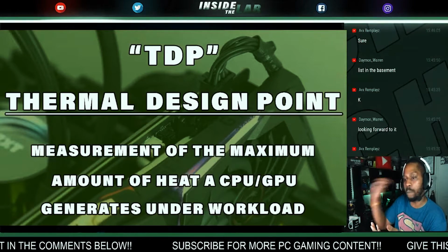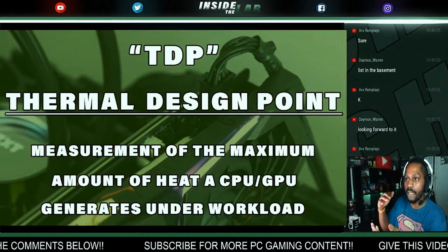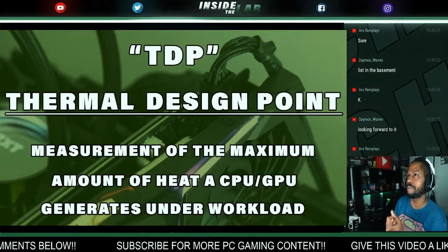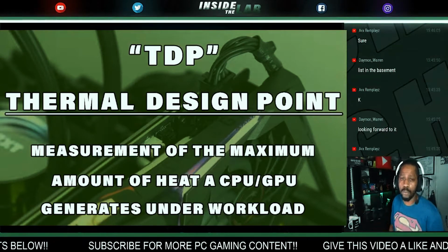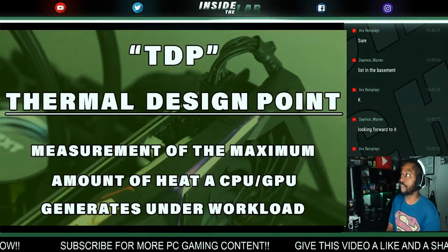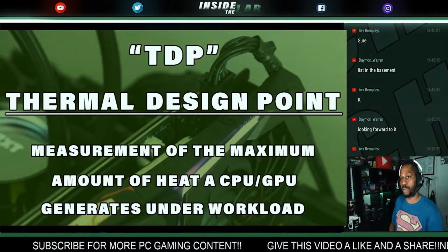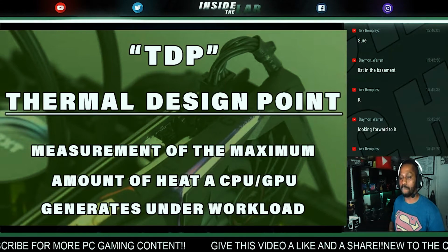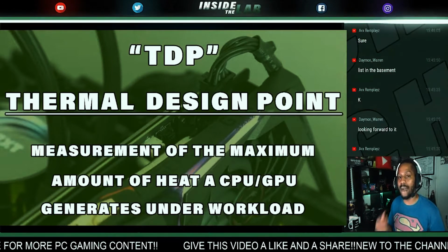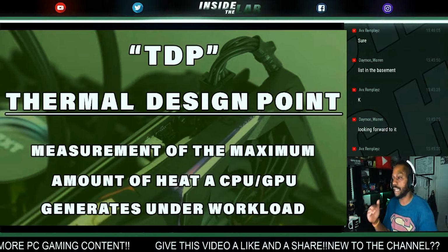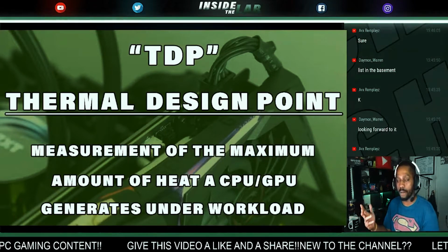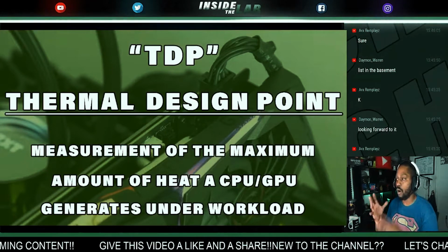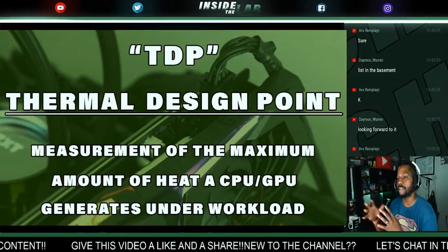I believe the clock speed is 3400 megahertz, 3.4 gigahertz, is what it'll top out at. So no amount of cooling is going to help you break that threshold. The CPU has a bin TDP that will only let it get so hot to reach that clock speed and no further.